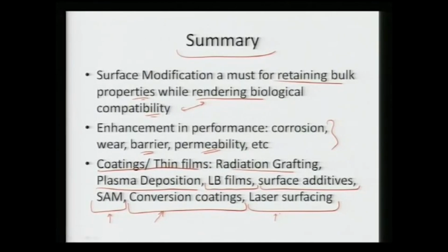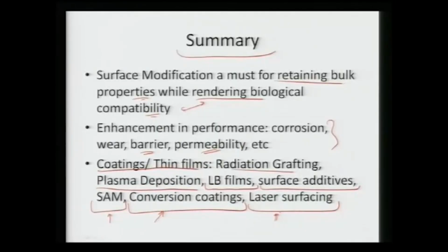And again we can have laser surfacing or laser engineering to coat a particular surface and somehow control the cross linking or polymerization of the surface and provide certain gradient in terms of the overall functionality. It can be hydrophobicity, hydrophilicity, or even certain barrier nature, corrosion resistance, even deposition of the films.